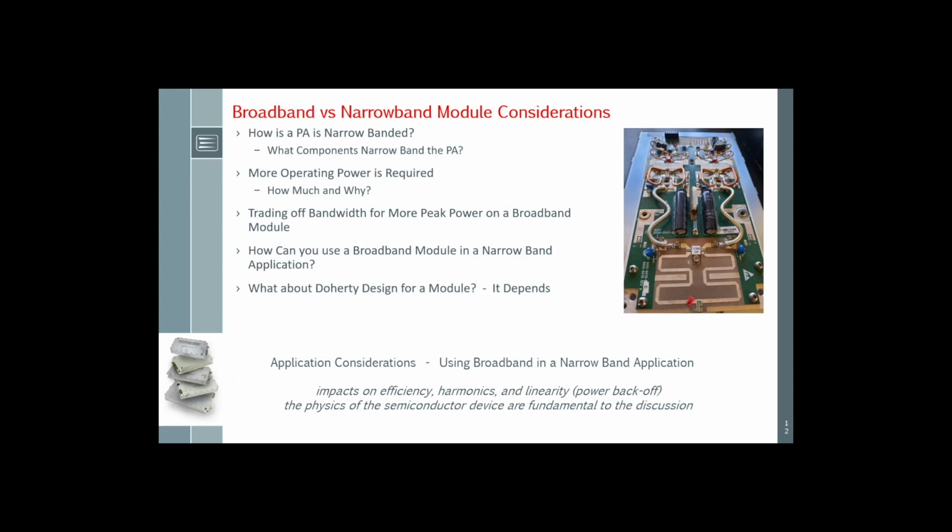Okay, so that's easier to match to the input, but that limits the higher frequency of the band. This is something that the designers consider when they build an amplifier. Matched amplifiers are very good to be used, for example, in narrowband applications. Per se, S-band, C-band, X-band devices are matched to those bands.